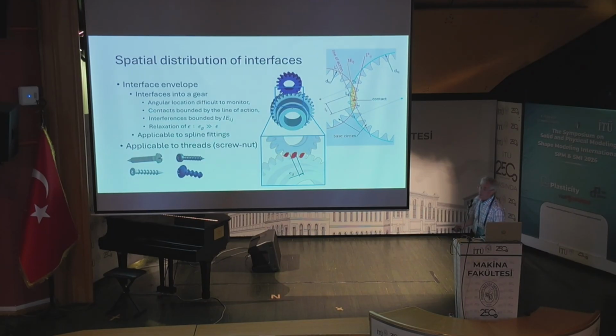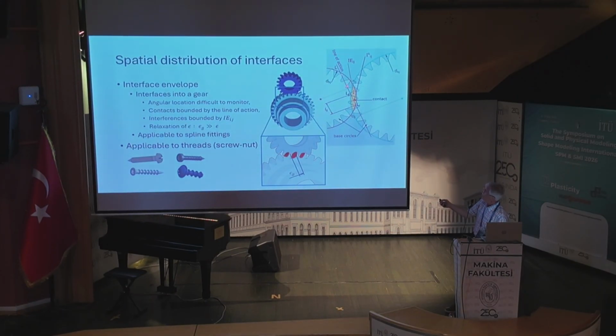Here, what we propose is to introduce the notion of interface envelope. This interface envelope is the domain that you see here in orange, and within this domain the line of action that appears here is the basis of the meshing process between the wheels, the gears.